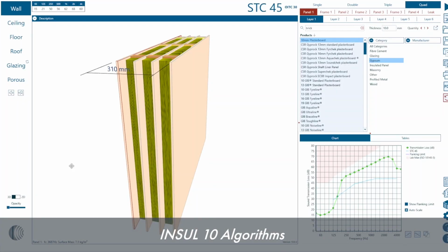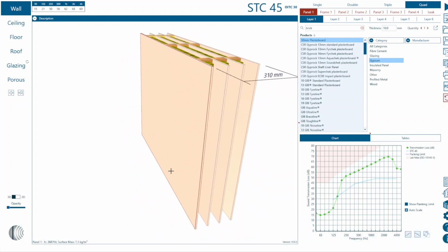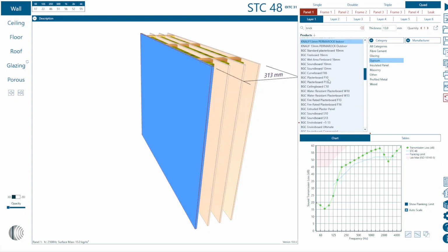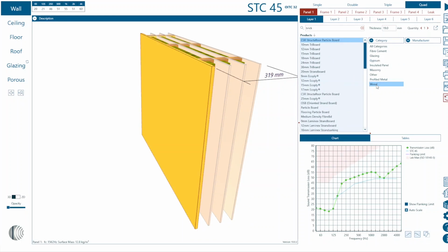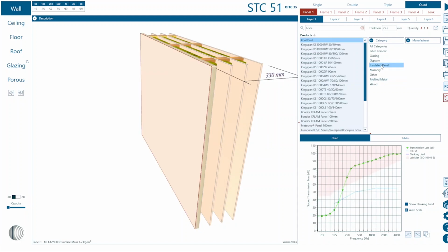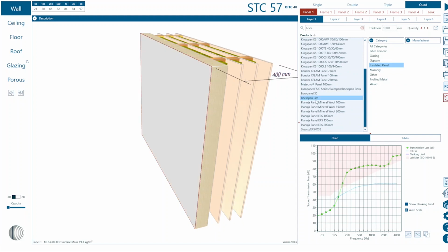The algorithms for INSUL's quad model implement a diffuse field airborne sound transmission method using a combination of longitudinal, bending, and shear wave models for the airborne sound insulation performance of homogeneous isotropic panels. Other panel types, such as orthotropic panels and sandwich panels, are accounted for by amending the classical models across appropriate portions of the assessed frequency range.